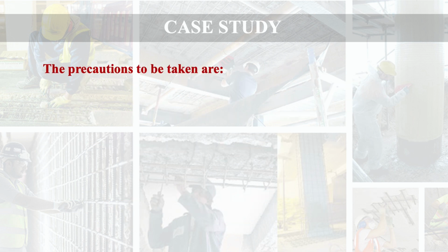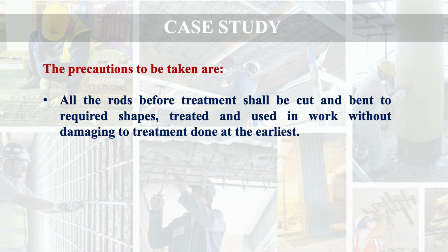The precautions to be taken are that all the rods shall be cut and bent to the required shape before treatment, then treated and used in the work at the earliest without damaging the treatment done.